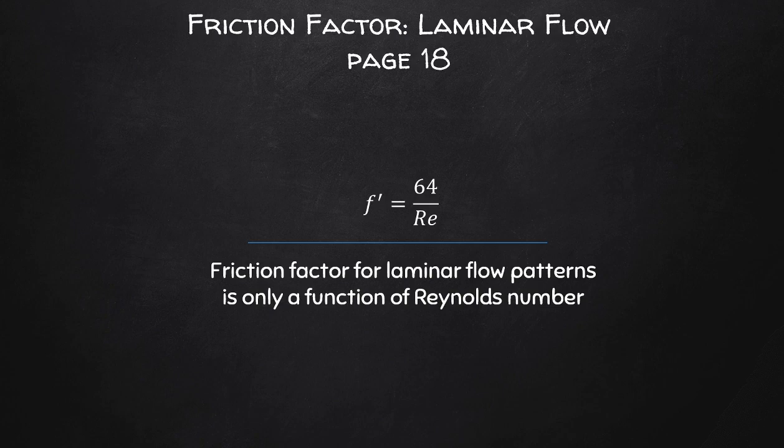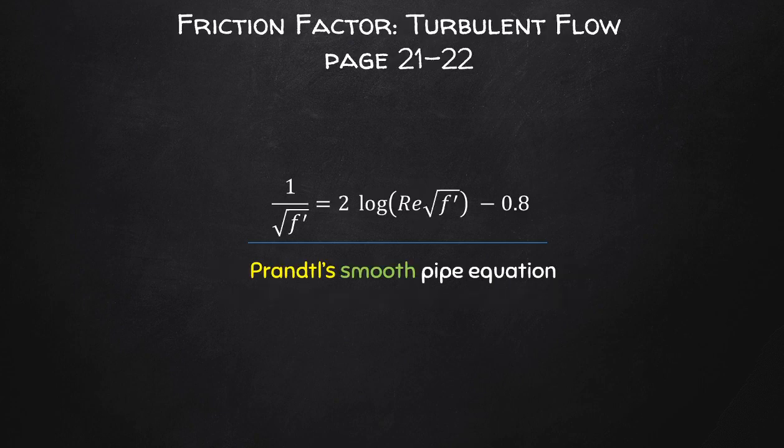Now, let us focus a bit more on the equations which describe these frictional losses in the pipe. I think you would have come across the particular one shown here for laminar flow. So the friction factor is often used with the Darcy-Weisbach equation, and in this case we would calculate this friction factor F prime as a ratio between the value of 64 and the Reynolds number for the fluid flowing through a pipe. For different flow regimes, we have a few more options to calculate the friction factor, and these depend not only on the type of regime, but also on the type of pipe being used.